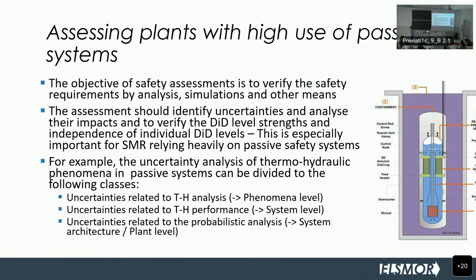When we start to assess this kind of system, we want to verify the safety requirements, the defense in depth levels, and the independence of individual defense in depth levels. But when we look at thermohydraulic performance, for instance, there are uncertainties on many levels. There is the phenomenal level: can we actually know what happens in very specific places and conditions?